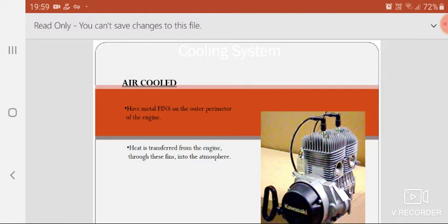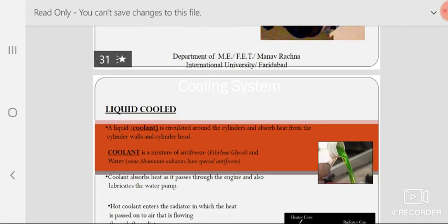You can see in case of two-stroke engines like scooters, etc., the fin structure is there. Because it is a small engine, air cooling is possible. That is simple natural air cooling, without a fan or anything. But in case of big engines, you need an external fan like you have in your cars. There is a radiator fan. But remember, whenever you are using a radiator fan, a lot of power goes into pumping the coolant, and a lot of power goes into running the fan. That is one aspect of that.